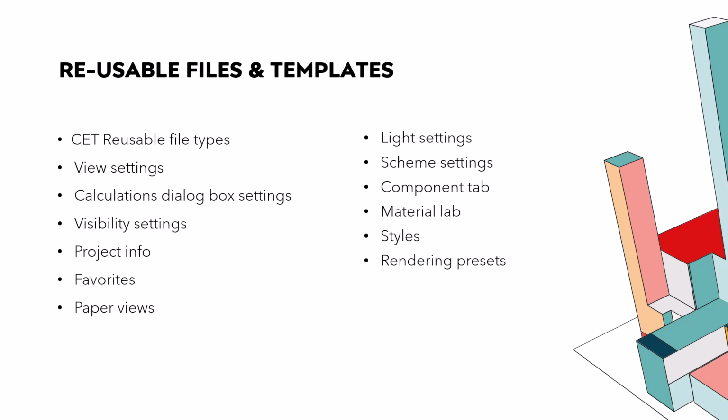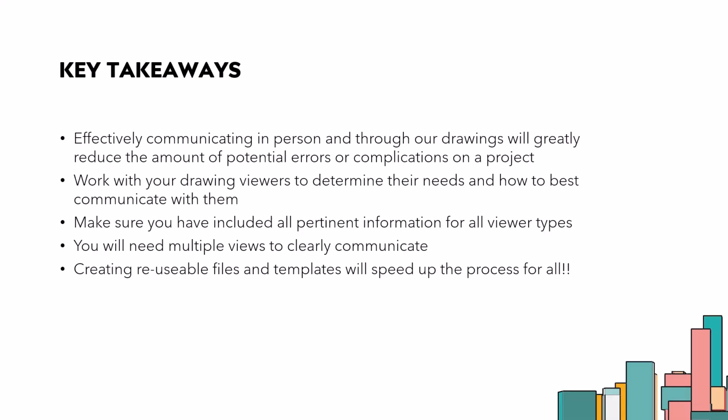Reusable files. Once you've already got all this stuff figured out and set in your drawings, you can save them and reuse them, and I highly recommend doing this. It's a great way to not have to repeat those steps over and over and over again, and it can be saved and shared with everybody you work with so that you are all using the same standards, and you're saving everybody else some time. And again, all of these on my screen are reusable files that can be saved into those templates, and then everybody can be working off the same template and using all of these. Make your drawings all look the same and communicate the same level of information.